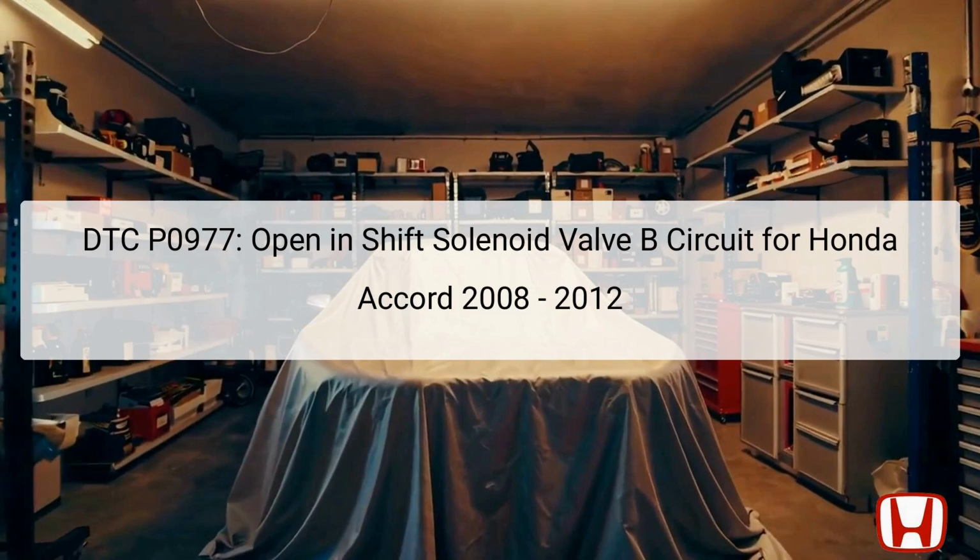Hello everyone, today we will be discussing DTC P0977, which stands for Open in Shift Solenoid Valve B circuit. This error code is relevant for Honda Accord models manufactured between 2008 and 2012. The primary component involved here is the Shift Solenoid Valve B, which is crucial for controlling the flow of transmission fluid in the vehicle. If there's an issue in this circuit, it may affect the vehicle's shifting performance, leading to erratic or improper gear changes.